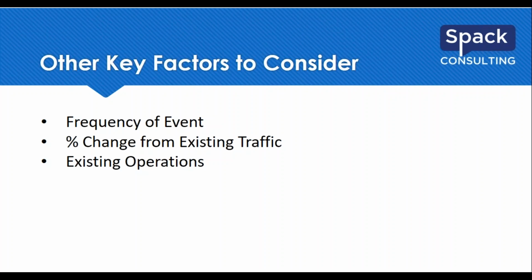So the 30th design hour, if it's just a one-time event for a couple of hours, obviously that's not the 30th design hour. But at a church that's happening every Sunday morning, that could become that 30th design hour. Yeah. So that's what this is getting at. And something like a state fair is starting to straddle that line if it's happening, or a county fair that might go on for a weekend, or depending how busy it is, or some type of amphitheater event that happens half a dozen times a year. But that's usually our starting point, is this 30th hour concept.